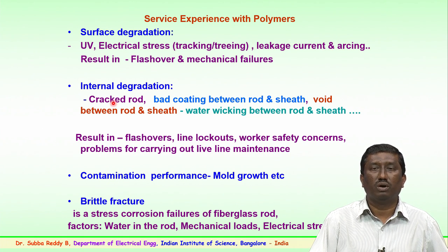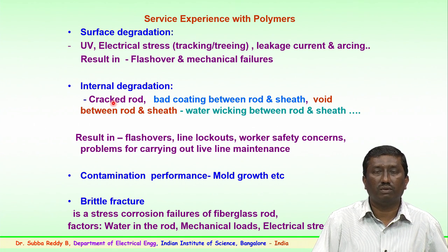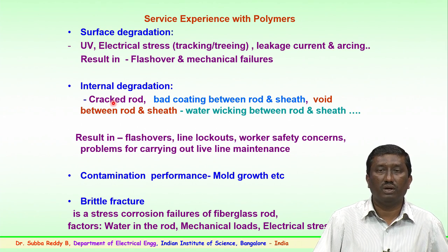blowholes or holes. In case of water entering the surface of the rod, the formation of nitric acid is seen, and because of this nitric acid, rod and sheath failures have happened, where brittle fracture of the insulating rod could occur over a period of time. So, these have also been seen in the field.